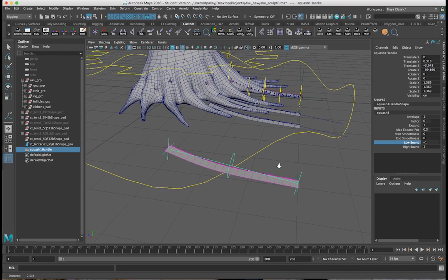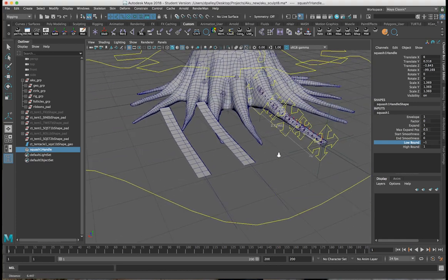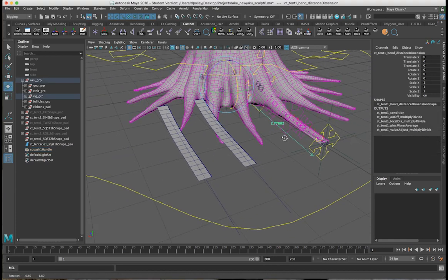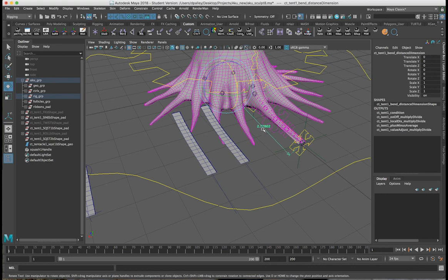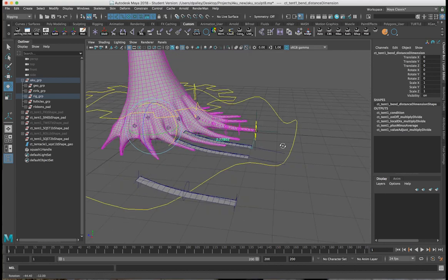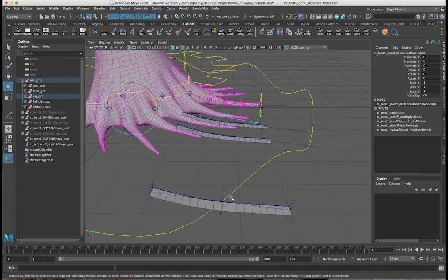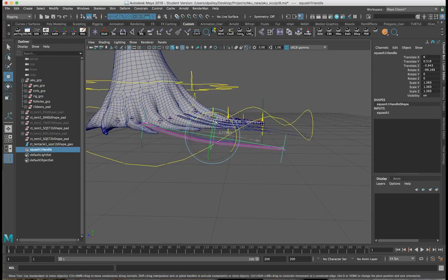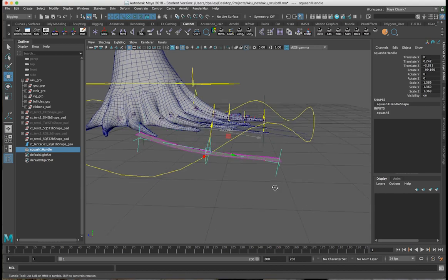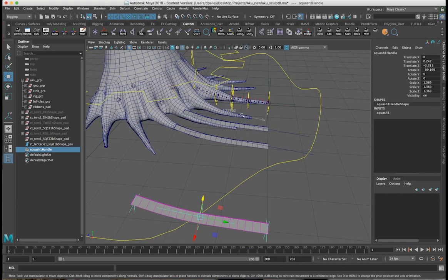In order to do that, because we already have this handy dandy little distance tool that we used in the original setup for the ribbon, we have this distance variable, which is exactly what we need, because this is the length from the root to the end of the tentacle. And the easiest way to set this up so that it'll squash and stretch with the existing rig is to make the handle here the exact same length as the stretching. So we have a 1-to-1 ratio there.